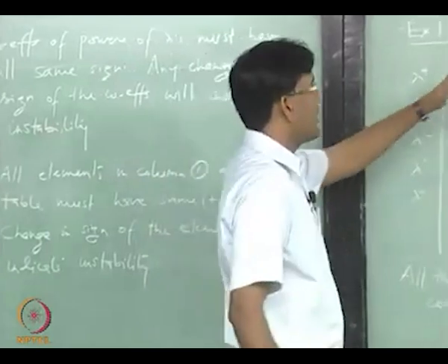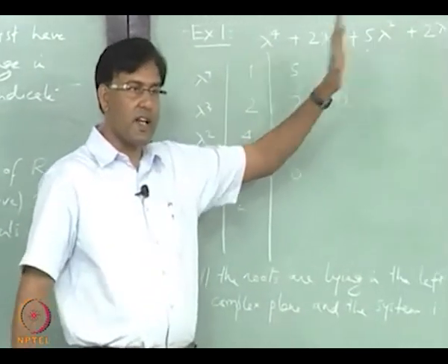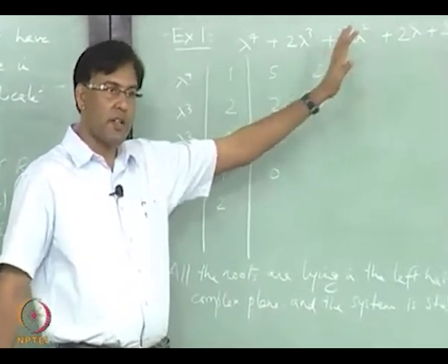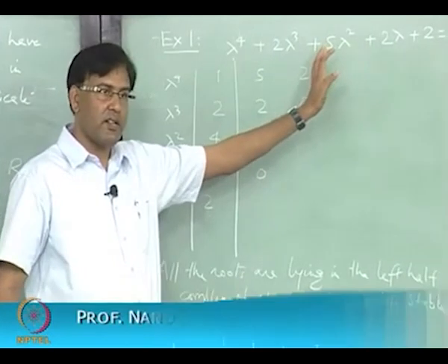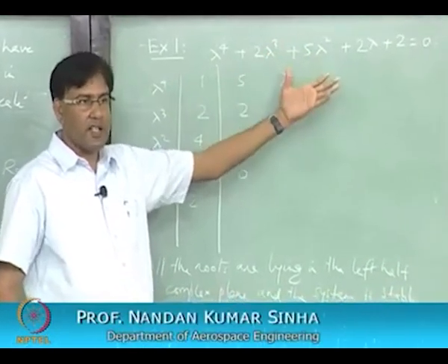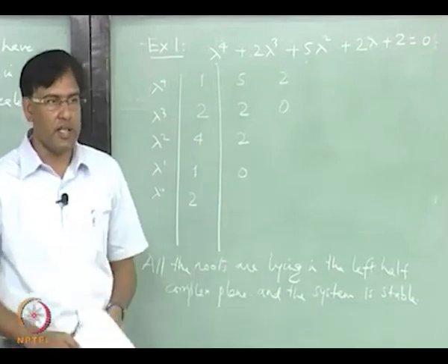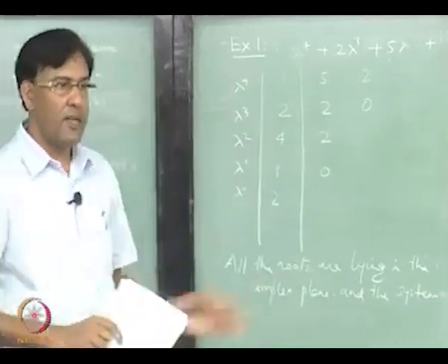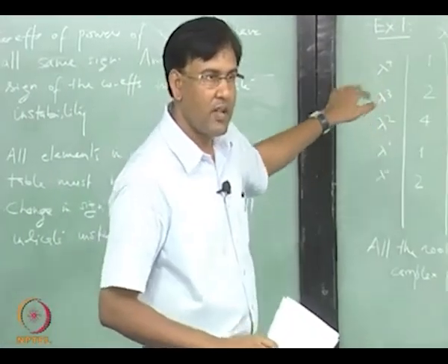No, if so, that is the first condition. Necessary condition is that all the coefficients must be having the same sign. If at the first stage itself you see that there is a change in sign, then it is unstable, okay, without going to the next step.